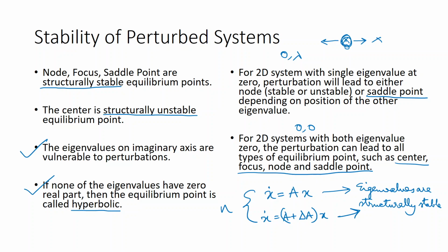If the order is 2, then we can draw the phase portraits. If the order is not 2, then we cannot draw the phase portrait, but we can analyze the eigenvalues of the linearized system, and if there are no eigenvalues with zero real part, then we are fine to ascribe the stability behavior of the linearized system to the perturbed nonlinear system.